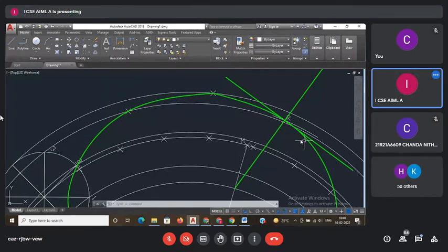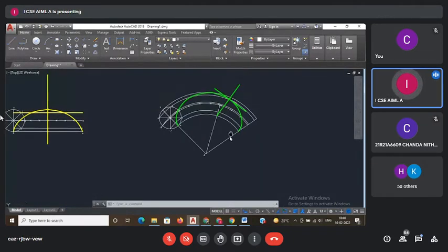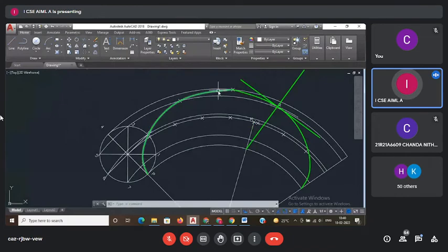Okay. Same hypocycloid, instead of convex shape, you will get concave shape. For that also you have to take notations opposite of the rolling circle direction. So as the rolling circle is rolling clockwise, you have to take notations anti-clockwise. If it is anti-clockwise, you have to take clockwise. Automatically you will get the points.